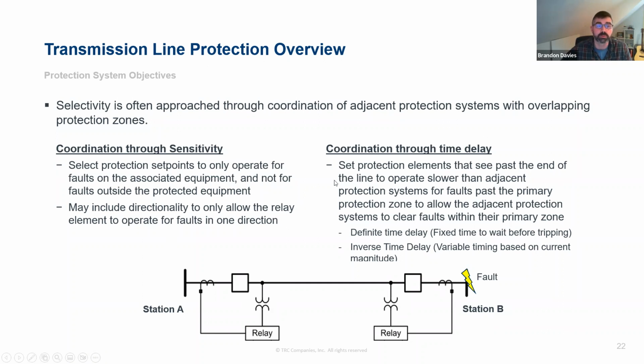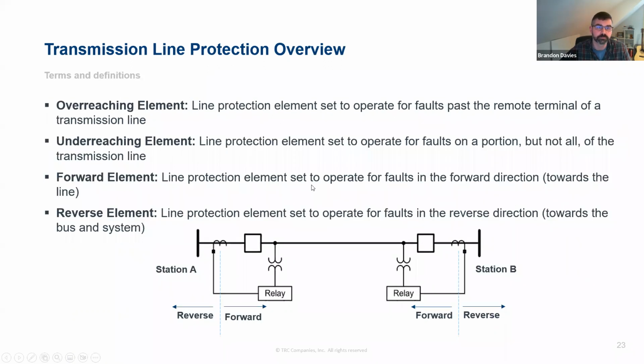So with the distance protection and the directional overcurrent protection that we would apply, we're going to be using a mixture of adjusting the sensitivity of the relay elements and adjusting the time delay on those elements. A couple other terms before we get into more of the protection details: some of the terms we'll use for our protection are overreaching or underreaching elements.